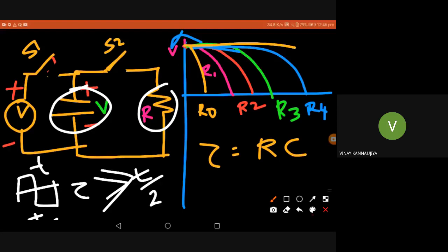Another question is whether charging and discharging are both instant. No, discharging is not fast. Charging is fast. Why is charging very fast? Because in the charging circuit there is no resistance. When the capacitor is charged through the clamper circuit, there is no resistance in its path. So charging is instant and discharging is not instant. Discharging is very slow. That is up to the designer.